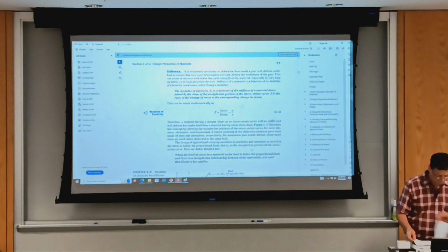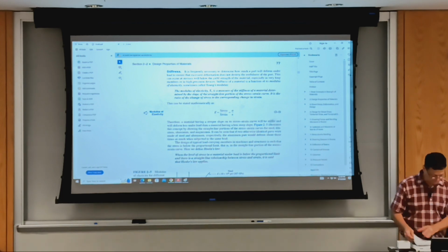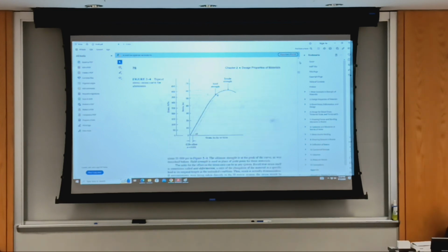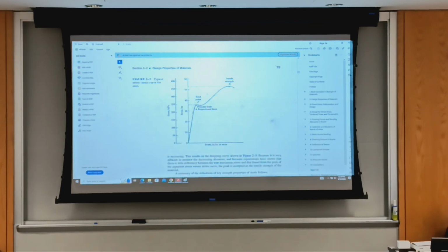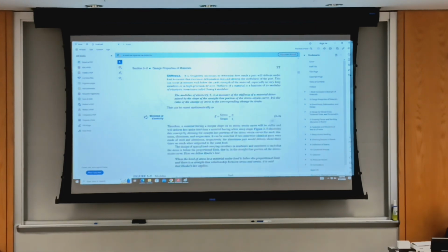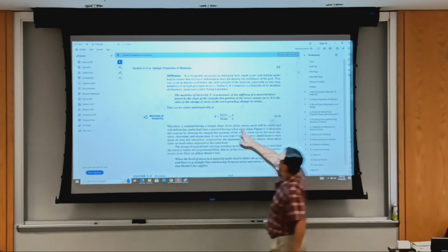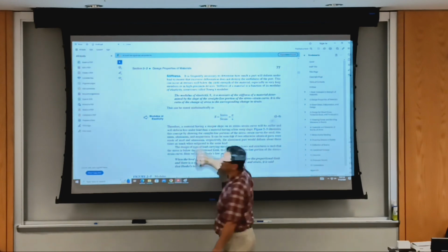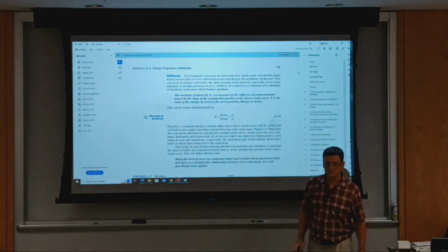Okay, we discussed percent elongation. Or let's discuss it just a little bit regarding the proportional limit on the graph. On this one it's not shown, but on the earlier one, it says proportional limit, where this is a straight line. The stress strain equation that you write this way has a slope of that line. It's noted E, and it's the modulus of elasticity, or Young's modulus of the material.